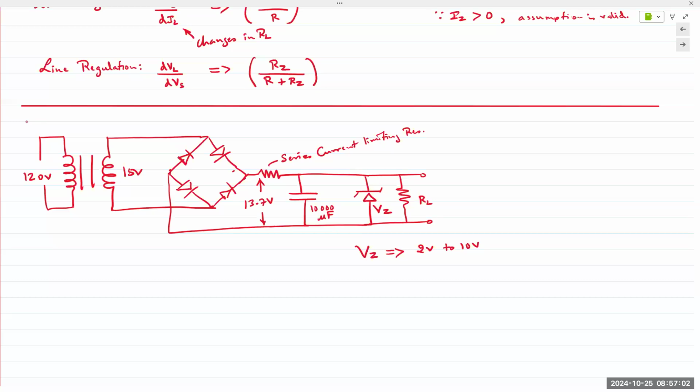Yes. So the capacitor is in parallel with the diode, right? But doesn't that mean the capacitor is not discharging? No. It's still discharging, but it's discharging into the resistor, not the diode. Well, that's a good question. The question being asked is whether the capacitor discharges through the Zener diode or not.